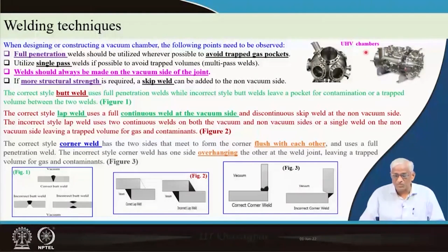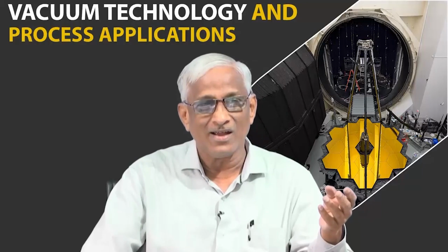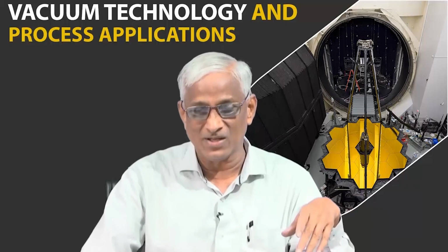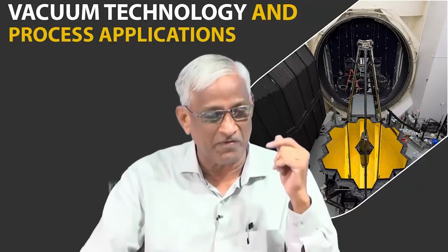So, typical vacuum chambers, particularly ultra high vacuum, look like that. Why am I showing UHV chambers? If you are used to UHV chambers, you can easily make HV chambers, you can easily make normal chambers. If you are used to deciding high quality stainless steel with minimum thickness with proper design for stress calculations, etc., you can easily purchase mild steel and make chambers. So, you should be mentally prepared for the most difficult aspect of it, where even micrograms of gas are not allowed to leak in. So, welding should be perfect.